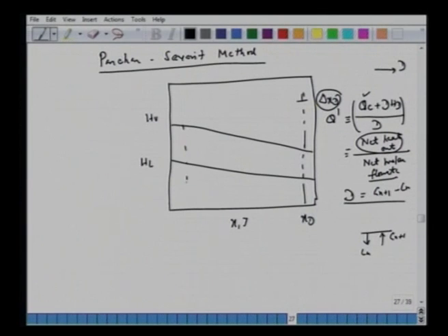Similarly, we did the same thing for the bottom product, where we had this xw, and we said that q double dash corresponding to this del xw point equals w hw, that's the enthalpy leaving the system, minus qb, since you are giving the energy here, divided by this w. So same definitions, net heat out divided by the net molar flow rate, w.